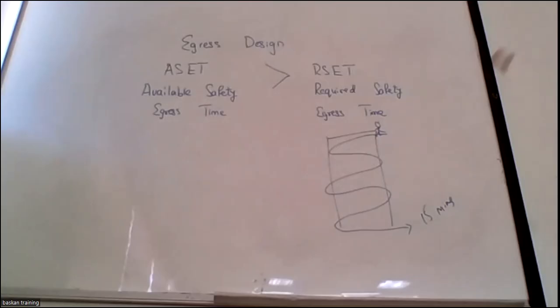That is why, whenever we are discussing why the evacuation times of buildings change, they have different types of evacuation strategies just to cover that time. Each and everything is related towards the evacuation time. Your doors, horizontal exits, okay, NFPA 101 indicates horizontal exits to have a minimum of 2 hours of fire resistivity. Why?